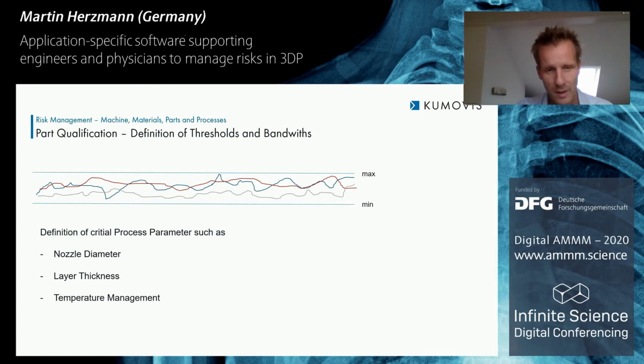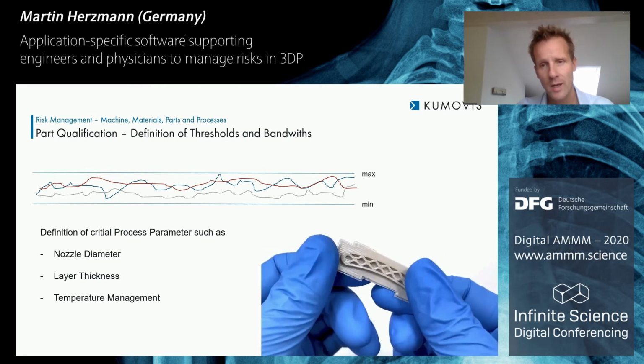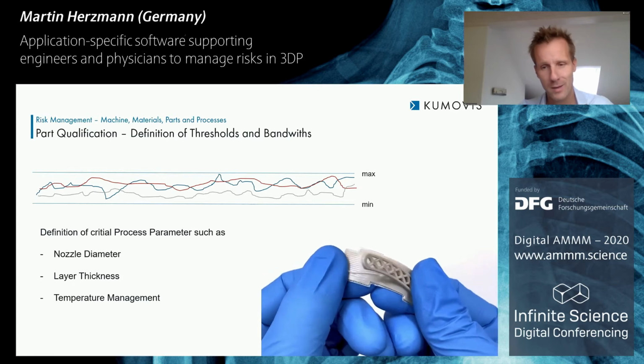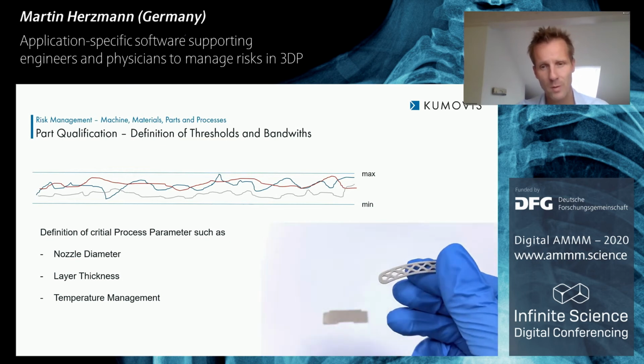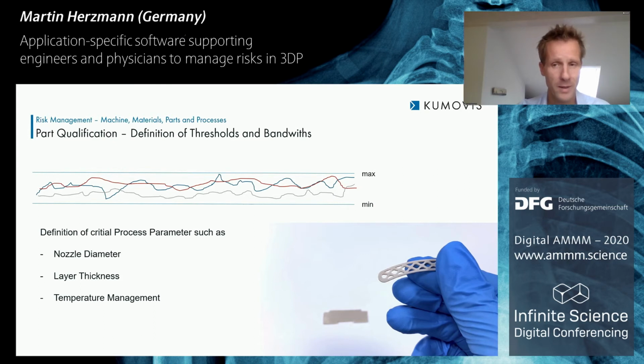In regards to temperature management, I would like to have a little deeper look. Temperature management is key, because temperature management for high performance polymer is one crucial and one key component. In this case, which I show you here, we have defined a mechanical property and a geometry and are able to peel off the support material without any tool, because we have defined in cooperation with the customer the shape and the size and the thickness of this print bed of this part. And by doing so, we are able to bend the part, the final medical device part, and can peel off this support plate which is laying underneath this part without any tools. But this needs to be defined in cooperation with the customer to allow, with smart temperature management, for example, ease of use once we talk about medical production in filament printing.